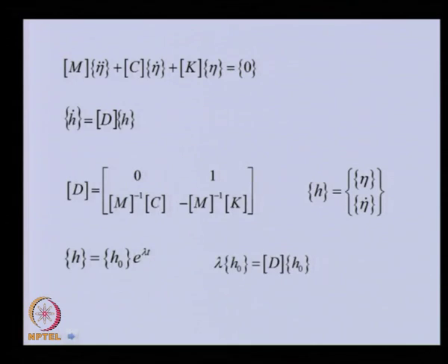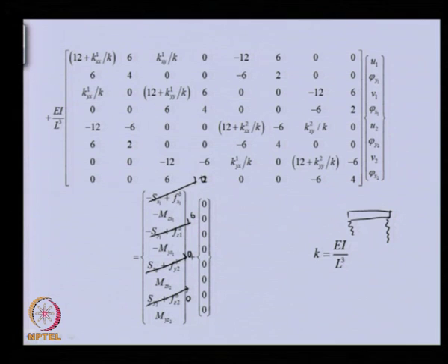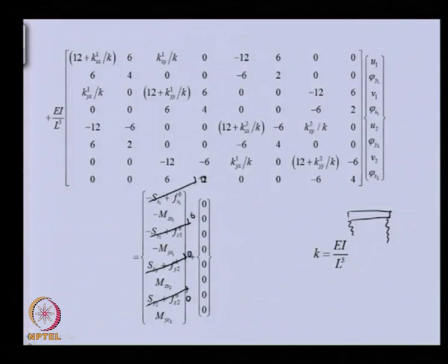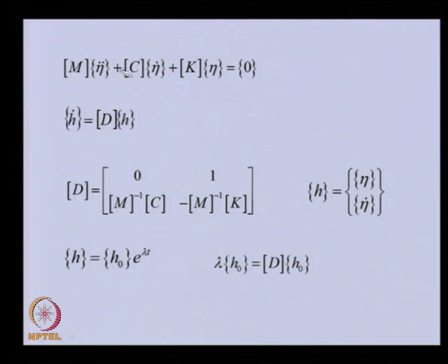So, basically if you see, this equation of motion is now of this form. Here, because this is a free end, the moment will also be 0 here. So, you can say these are also 0, because the bearing cannot resist any moment. So, this moment will also be 0. So, this is the form of the equation of motion.